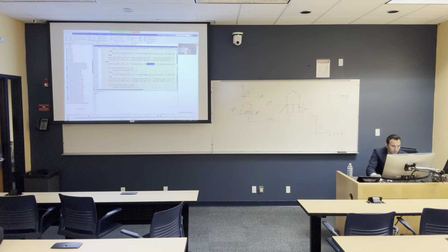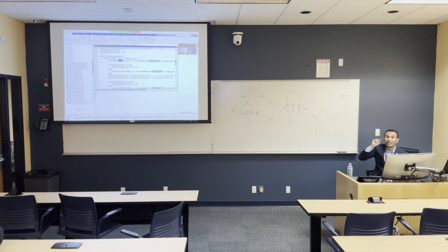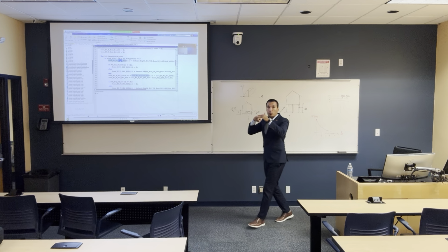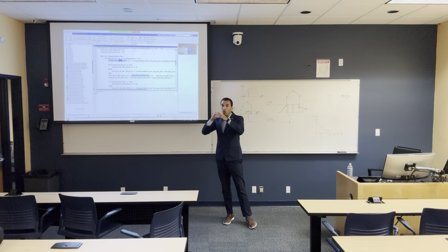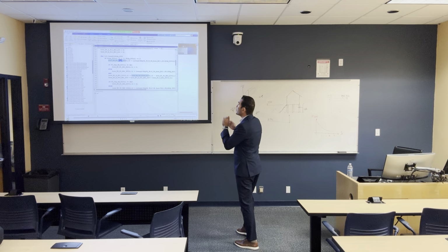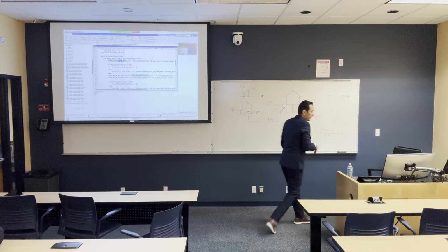Like if you look here, when we did the find and replace, you will find that this one has elevated components, and this is a base scenario. That's why I put base here to remind me that this is the base scenario without any mitigation, and I'm subtracting from this one. It cannot have elevated components, it cannot have flood duration, it cannot have a flood barrier, because that is the base that I'm calculating from, okay? So just change these two, basically I will delete this part.